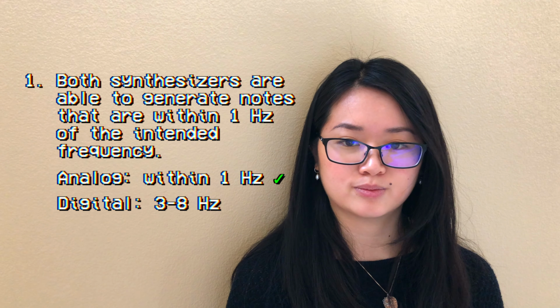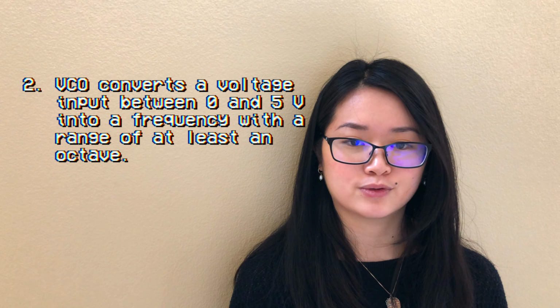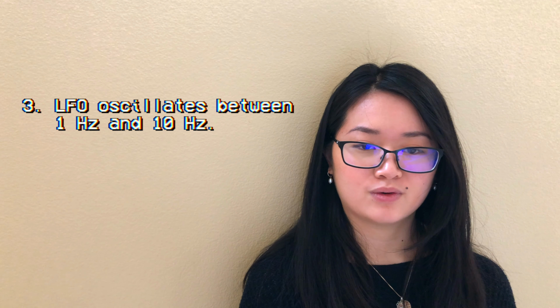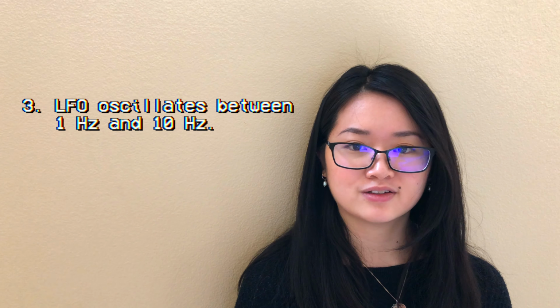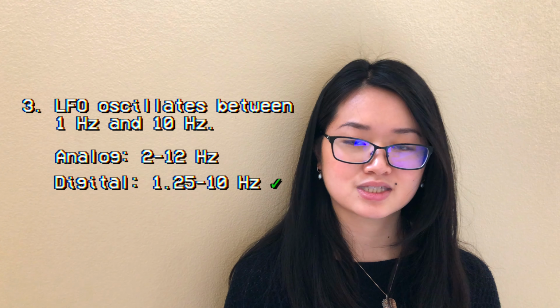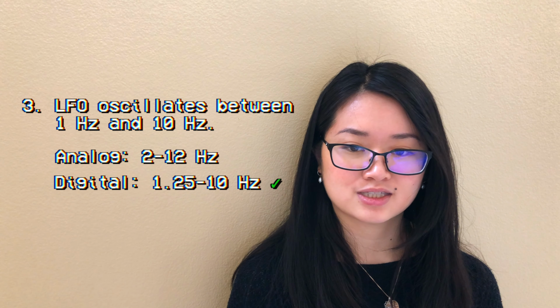Our second benchmark was that we could make a VCO that is able to convert a voltage input between 0 and 5 volts into a frequency with a range of at least an octave, and both the analog and digital are able to do this. In addition, we wanted to make an LFO that could oscillate between 1 Hz and 10 Hz. In practice, we got our analog LFO to oscillate between 2 and 12 Hz, and our digital between 1.25 and 10 Hz. Though these are not exact, we hit the rough range of our LFOs with success.